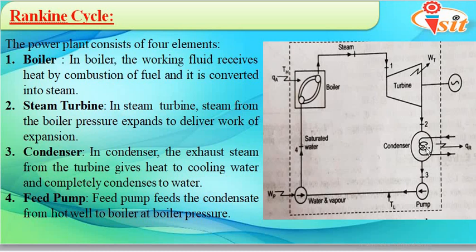As a result, the heat present in the steam coming from the turbine will be absorbed by the water coming from the cooling tower. So the temperature of this cold water will further increase and it will be fed back to the cooling tower for cooling.